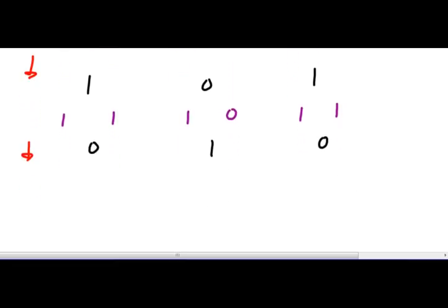All right. I look at it again, and I've got a 1 and 1 both there. I've got a 0 on my Q. 1, so I've got a 0 there. I've got a 1 here. And I've got a 0 there, and I've got a 1 there. So these guys are still in toggle mode. Okay, the clock pulse happens, boom. I get a 1, I reset to a 0, I get a 1.